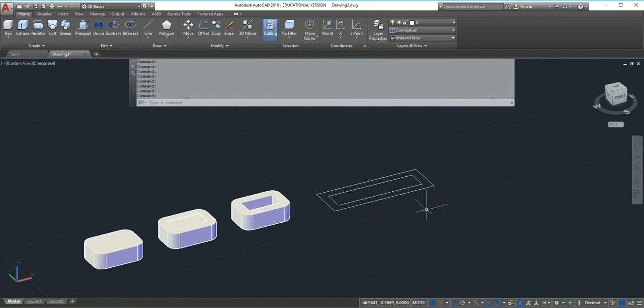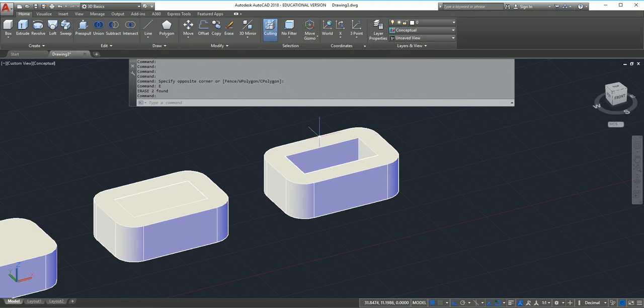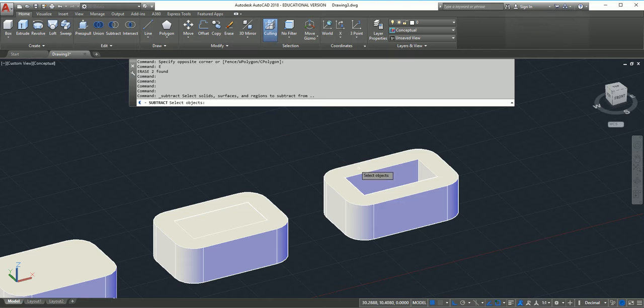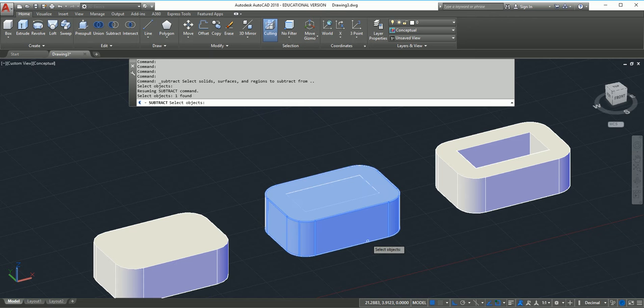Anyway, whatever. Alright, so flatten works differently because if a line, I could draw it. So basically, press pull is doing 2 commands at once. It's going to do the extrude and it's also going to do the subtraction. So if we go ahead and we do subtract, okay? Now, subtract is like trim, right? Imagine trimming a 3-dimensional object. So we want to pick what we want to keep first, and then what we want to subtract out second. So we're going to keep the outer one, so we're going to pick the outer one, okay? Hit enter.